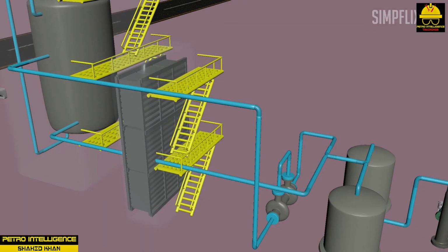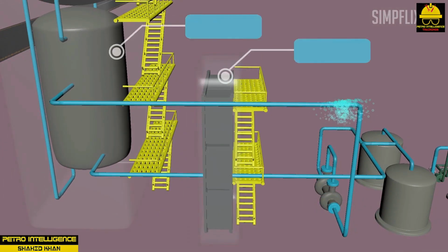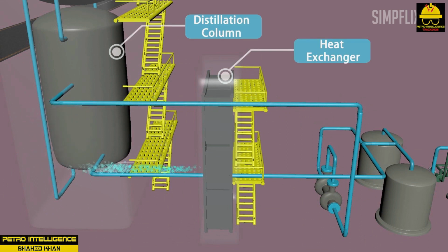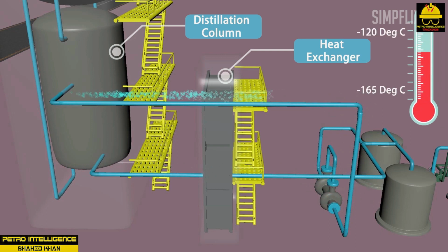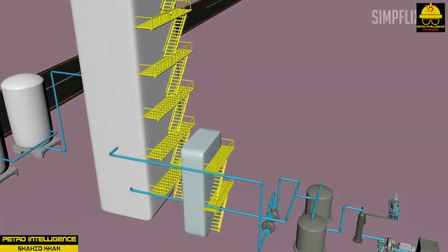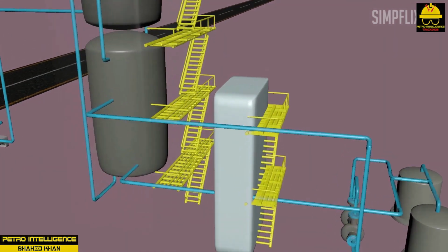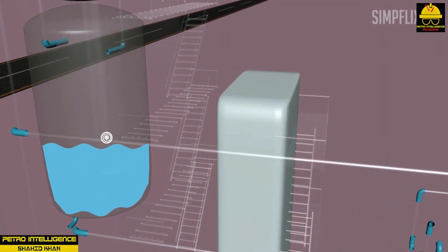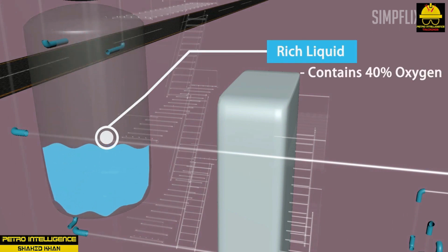As air enters the cold box, it flows into the main heat exchanger where it is cooled to -112 degrees Celsius. At this temperature, some of the oxygen liquefies and enters into the boiler where complete liquefaction occurs as the cooled liquid oxygen evaporates. Air leaves the boiler and flows into the top of the packed column where it is allowed to flow down through the packing material, giving up the lighter nitrogen gas.